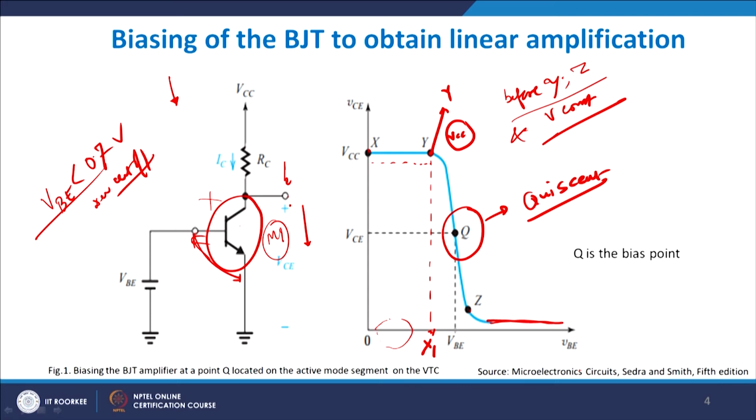See, if you look very carefully, if your device is biased here or here, you are either in input state 0, or you have got here a large input. So, a large input and a small input, I can show on the same graph, and this is how it is done. Before we show you how it is done, we will just comment on the fact that the points between Y and Z are so small a space from each other that they seem to merge with each other, but there are sufficient number of points to evaluate beyond Z and Y that this region is the high amplification zone, and these regions are basically your digital zone.